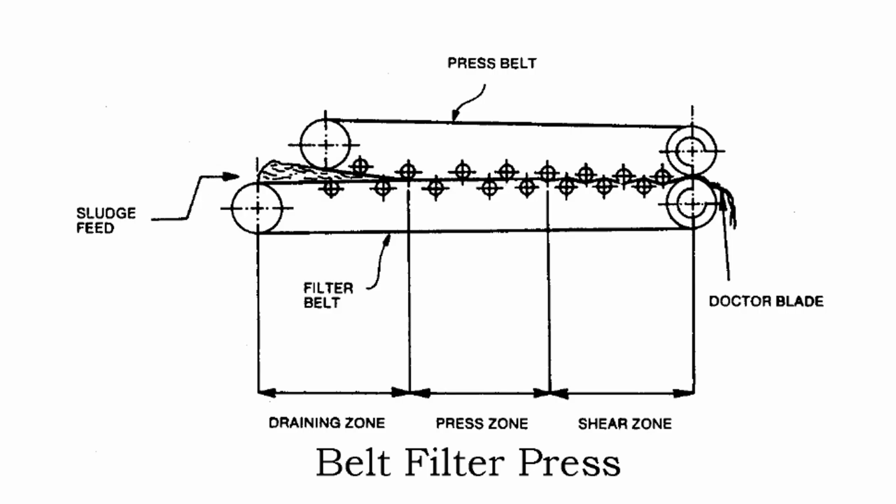This is a fairly low tech version of a belt filter press. This is the simplest method of dewatering as possible, and this is why I think it's so popular, because it is low tech. And what you basically have is your sludge from your thickener, your digester coming in, high amount of solids, and then you've got rollers here with a belt press, and they're all spinning.